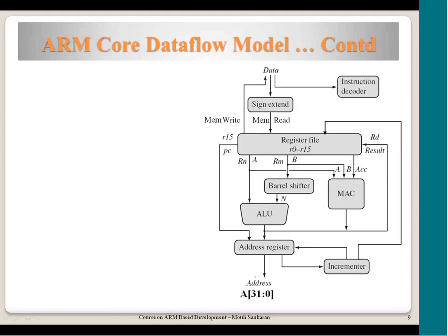Finally what is written into a register has to be 32-bit data, because I told you the instructions operate on only 32-bit values in the register. So even if the memory interface allows reading 8-bit or 16-bit data, that either gets sign extended or the top portion is filled with 0, and the complete 32-bit content of the register is used for any arithmetic operations inside the processor.